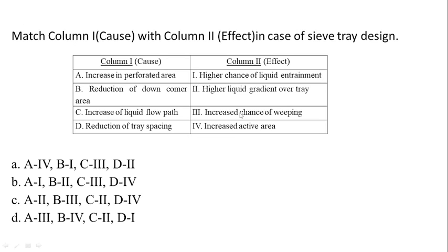Next one. Statement 1: height of tray tower depends on number of actual trays and tray spacing. Statement 2: height of packed tower depends on number of theoretical trays and HETP. Which of the statements is true? Option D. Both statements are true. Yes.